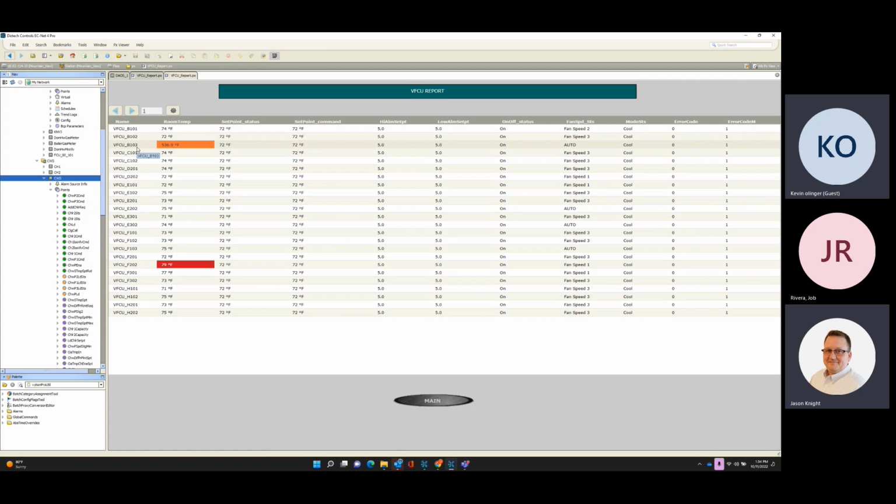Yeah. And I'm assuming that, let's say somebody overrides a DOAS on, or it stays on for whatever reason, and we're running into the night and it's 40 degrees out, I'm assuming that chillers aren't going to run, chilled water pumps aren't going to run because we've still got outside air lockouts for those. Same with boilers if it's super hot, right?